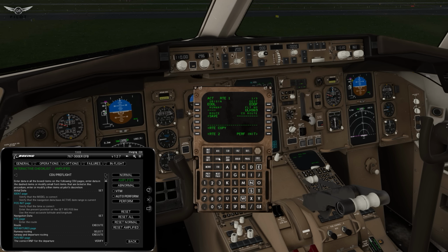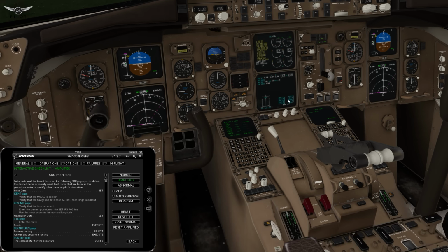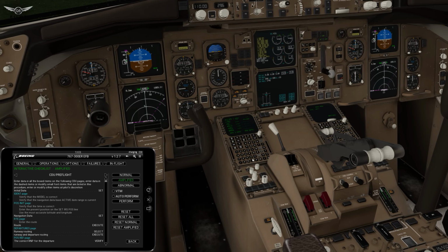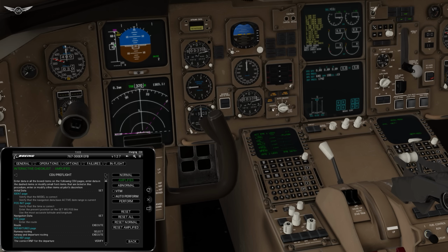And we're just going to take a look at the legs page, make sure there's one disco here from Rolls to Cole. Normally there is a waypoint Tango 150, but it's not valid for this particular AIRAC database. Execute, and we can now take a quick look at our flight plan to make sure that there are no strange things going on as we arrive.